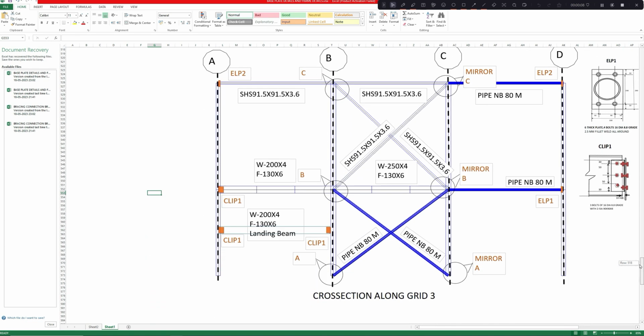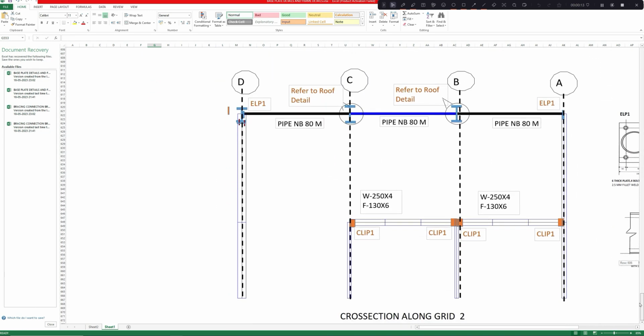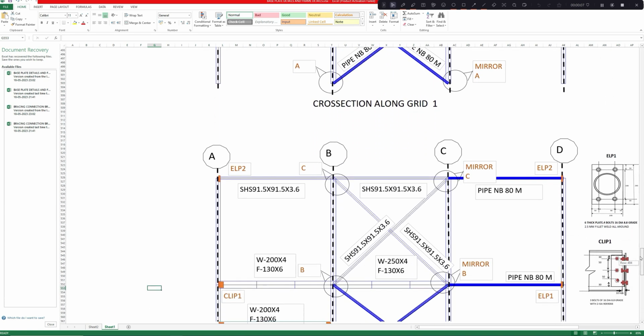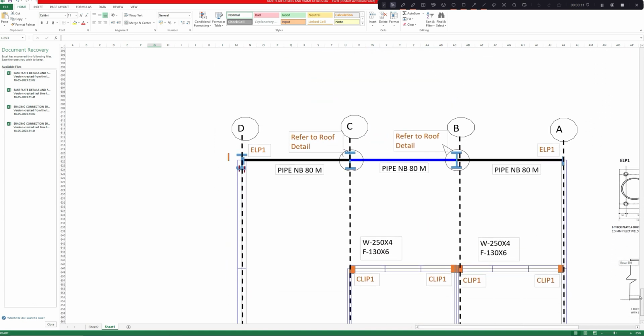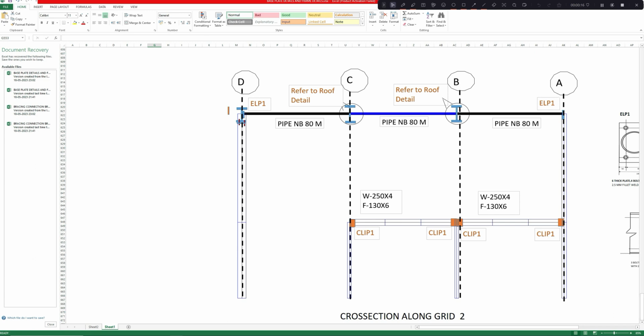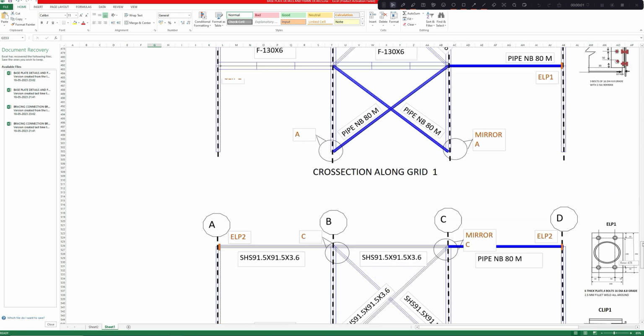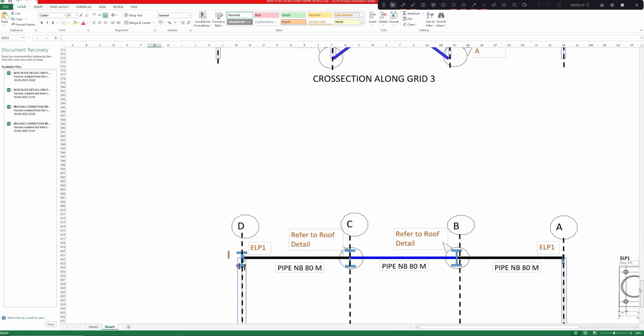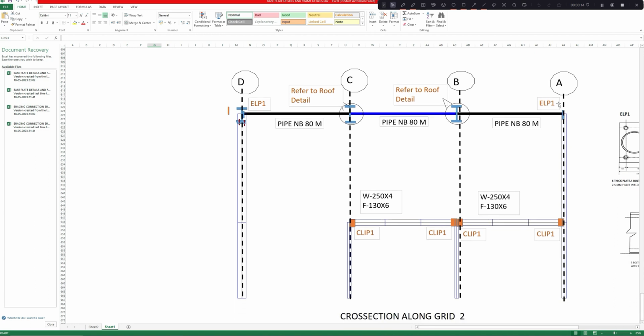Along with this, we have to give him certain more information, like if there is some brick wall at plinth level, or what is the spacing of girts and purlins, that we can provide in the form of notes to him. According to that, we will prepare the GA. And we need to have architectural elevations also showing the openings, so that the detailer provides the required cuts and details or purlin details according to the openings in the roof, if any, in the form of skylight, or openings like doors or roller shutters at all elevations.